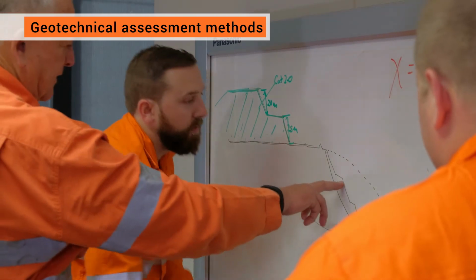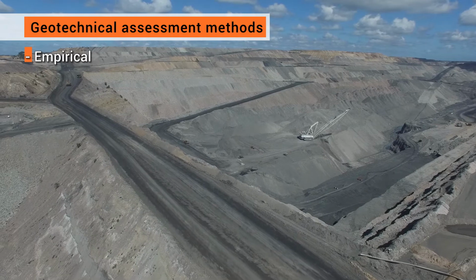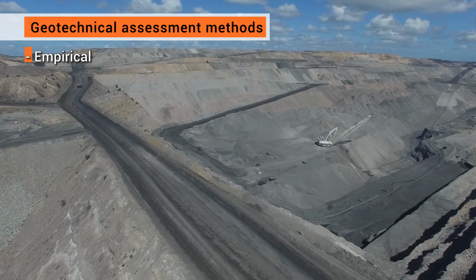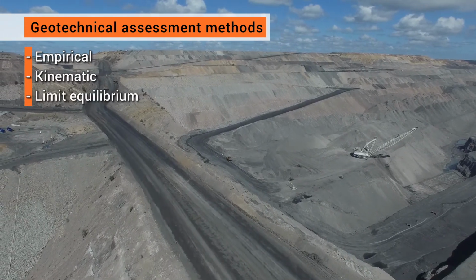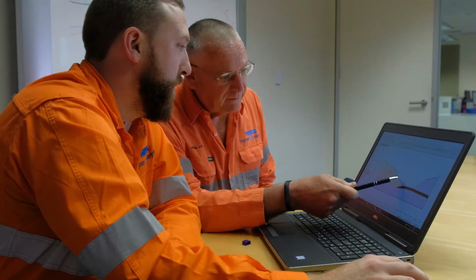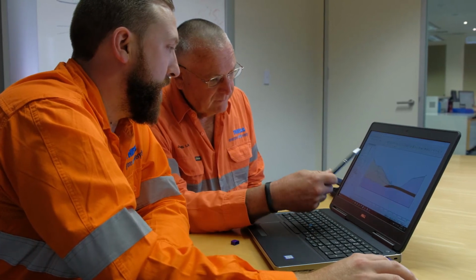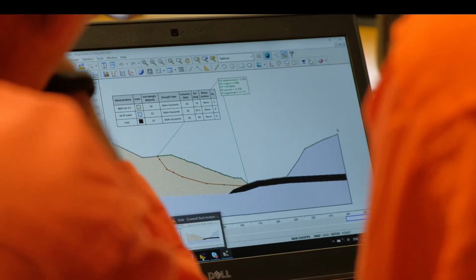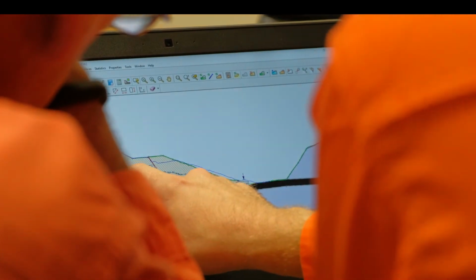The four main types of geotechnical assessment methods are empirical, using design charts or basing designs on the performance of previously excavated or dumped slopes in similar conditions; kinematic, limit equilibrium, and numerical modelling. Modelling results may be reported in quantitative or qualitative terms. Qualitative, such as likely or unlikely, or quantitative, such as factor of safety, strength reduction factor, or probability of failure.